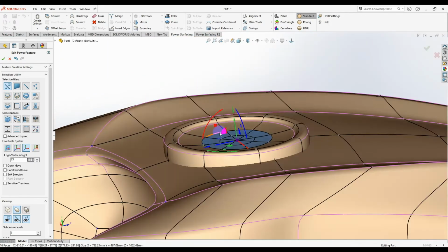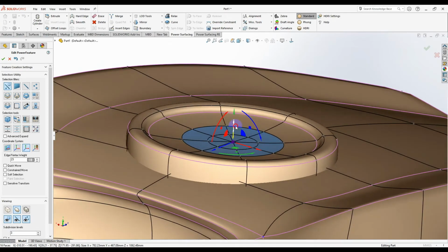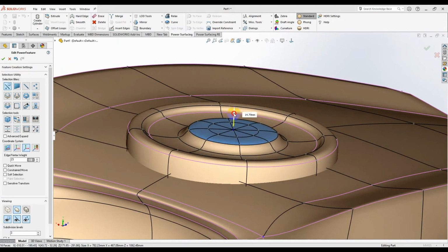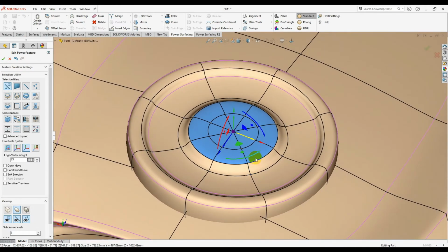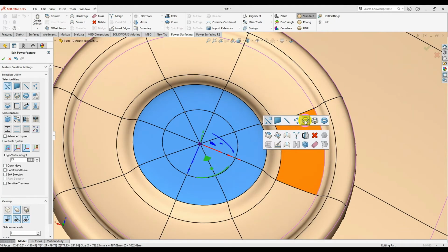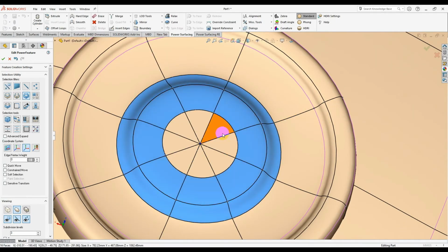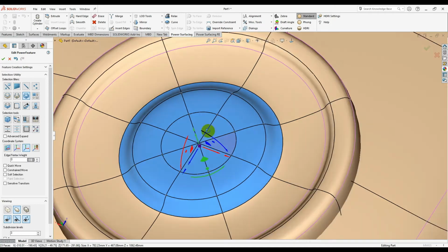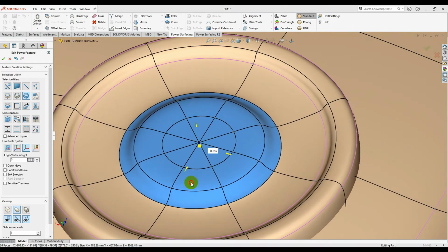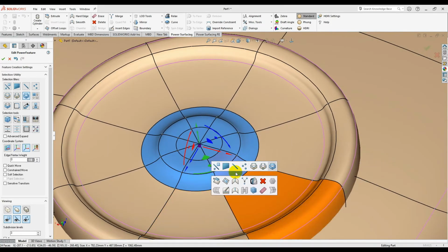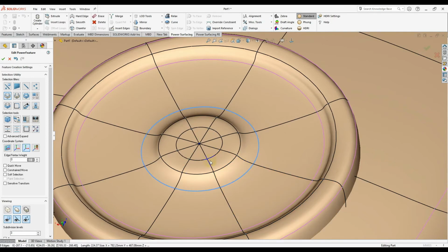So I think it's nice now. You can hold and create this small one, using all faces again, make it smaller, and using this edge crease it 33.